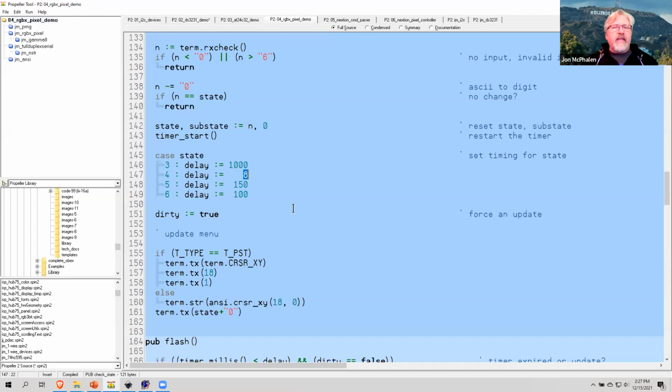So if I have a phase of 0, I have these two colors. A phase of 0 means all of this color. If I have a phase of 255, it's all of this color. If the phase is in between, then it's a blend of the two colors. That's why I call it morph. I wanted the change in my LEDs to go from one color to the next color in about 2 seconds. Well, if you divide 2000 milliseconds by 255, then it's about 8 milliseconds. So that's where that is.